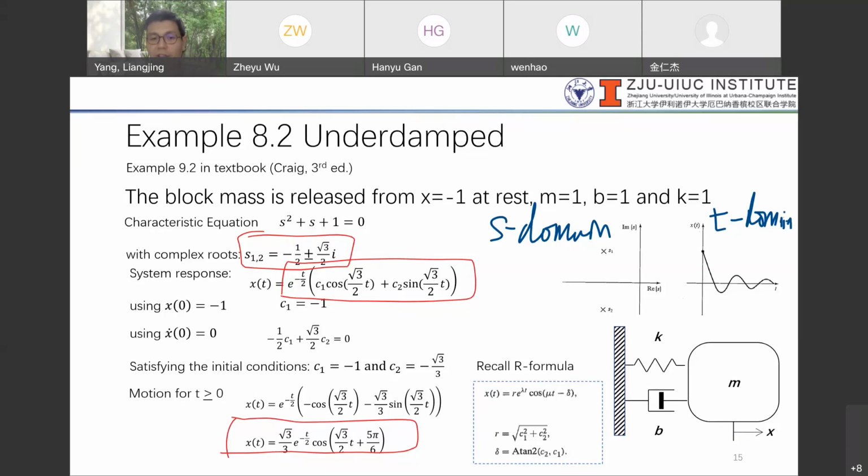In all natural systems, when it goes through a free response, it's going to be stable, if you don't put in a controller that is not well designed, because naturally there will be dissipation of energy to eventually bring the system to stability. So whenever you have something like this, it will be on the left half plane.